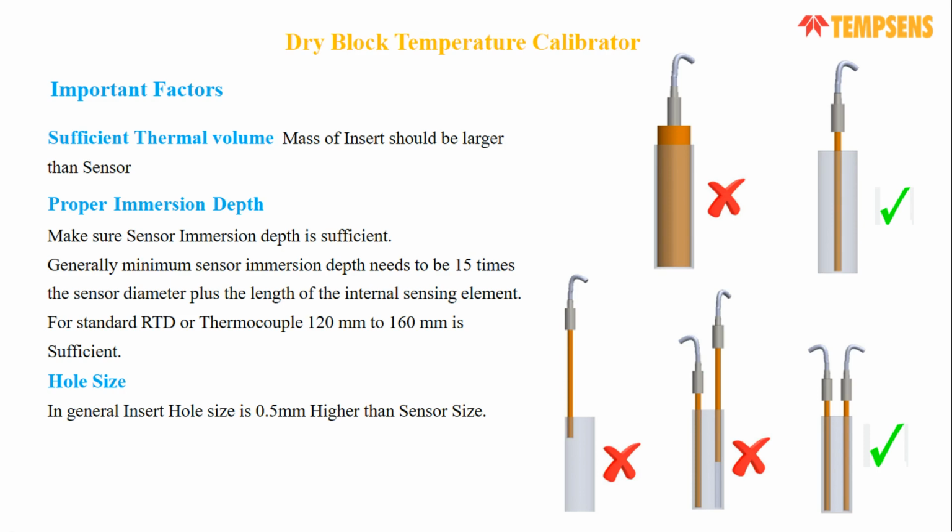The insert mass should be much higher than the sensor to give you the correct reading and a correct, uniform result. And the second factor should be your proper immersion depth.